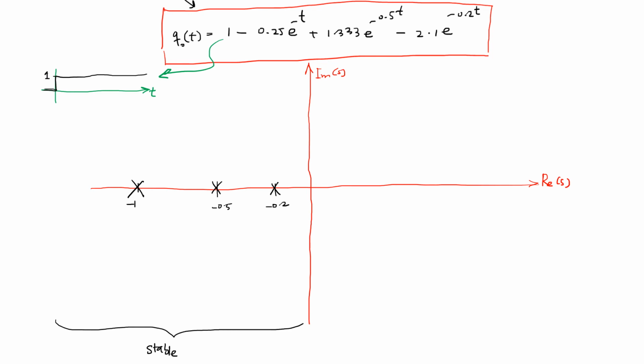So this is going to be one inference added in the system because of the input being given to it, like a unit step input. Let's try to see what happens with the second term. You can see that there is a coefficient of -0.25, so I can see that this component is going to start from -0.25, and then you can see how it is decaying. So you have -1 as the decay rate.